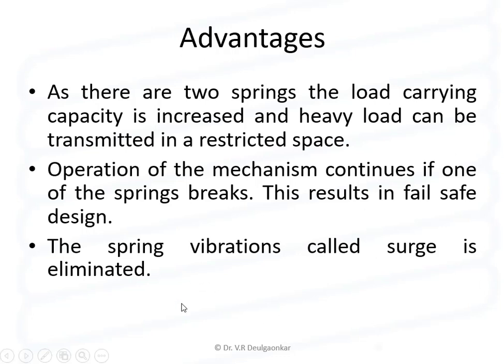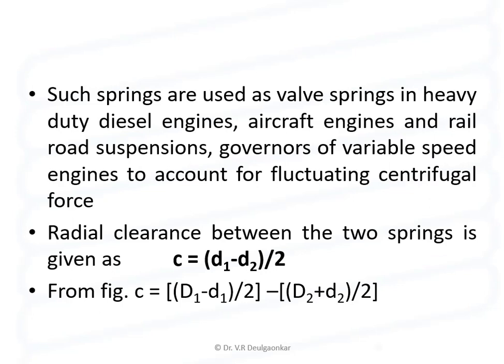The spring vibration, which is called surge, is eliminated. We will see this surge in a later session. Such nested springs are used as valve springs in heavy duty diesel engines, aircraft engines and railroad suspensions, and in governors of variable speed engines to account for fluctuating centrifugal force.